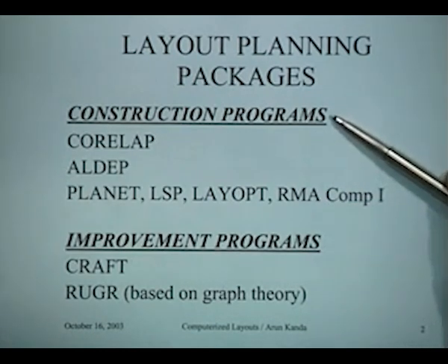Construction programs are those programs which try to generate the layout plan from scratch. That is, you don't need any initial layout as an input. By utilizing the information that is available about the layout, you can generate a layout from scratch.